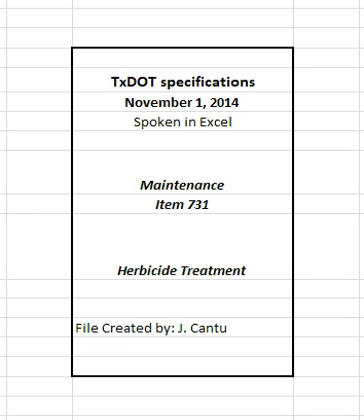Spray undesirable vegetation by broadcasting with spray nozzles at the desired rate. Spray from the pavement or roadside to reach the vegetation being controlled as approved. Ensure nozzles spray consistent across the area being covered.